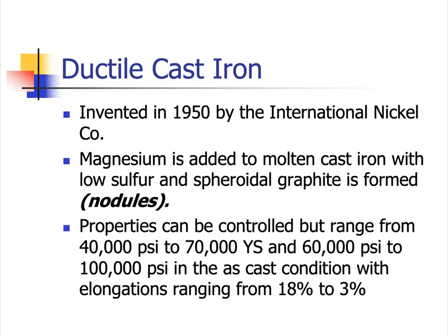And then along came ductile iron. Ductile iron was invented by Keith Millis around 1950, and he worked at the International Nickel Company. Imagine if you took Cocoa Puffs and milk and you froze them. Cocoa Puffs are completely spherical. Now if I take that out and make my tensile bar and pull on it, what happens? Well, the cracks that go across it, every time they hit one of those spherical holes with graphite in it, it tends to blunt the crack.